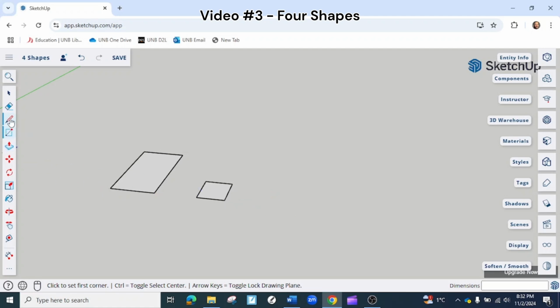I don't have a triangle tool, so I'm going to need to draw it by hand. So what we're going to do is select the line tool, this pencil right here. However, of course, you know me, I'm never going to come over here and click this. I'm going to hit the L. So I'm going to hit L, and now you'll notice that the pencil comes up, but it doesn't have a rectangle. Look at the difference. Here's L, here's R. It has that floating blue rectangle around it. So L is our line tool. It'll still let us hover and go in line with this, so that's what I'm going to do.